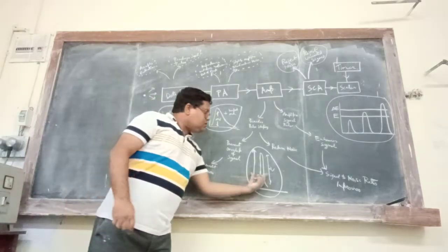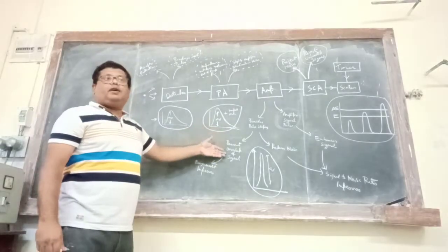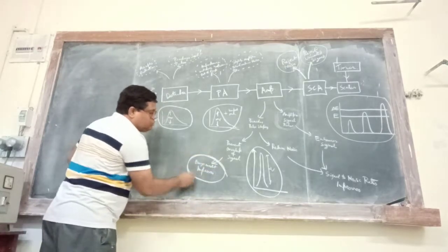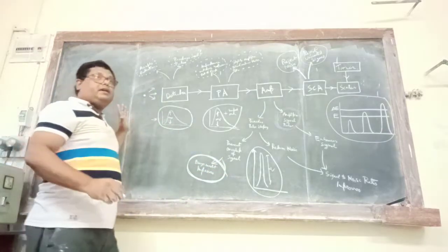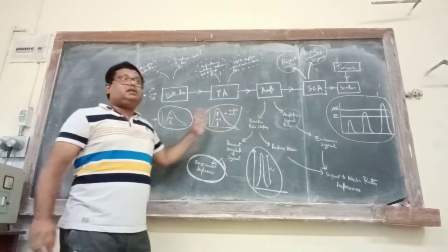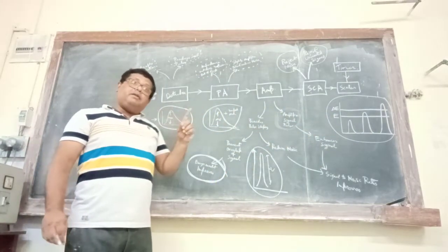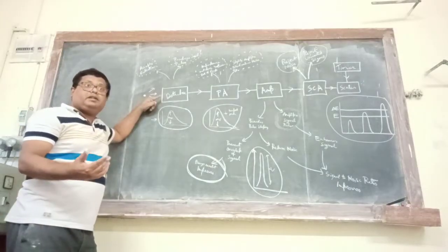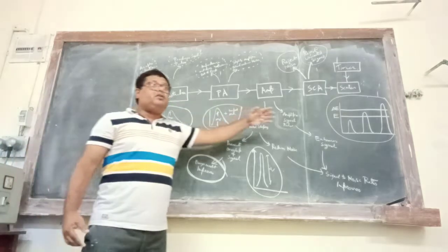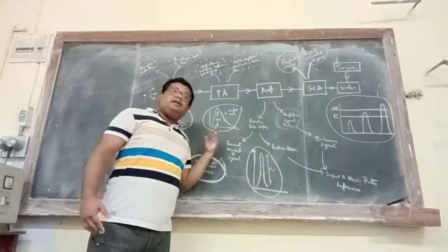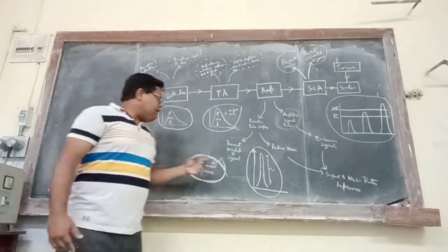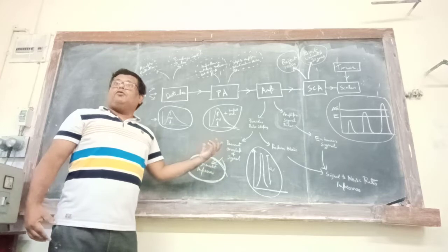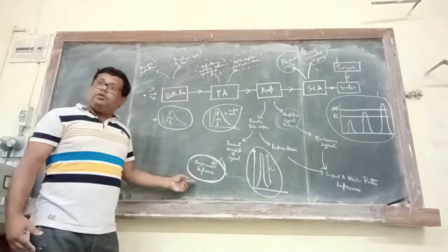And because of this, preventing overlapping of pulses, the energy resolution will improve. Overall energy resolution due to the counting system. Remember what I am saying. Previously I was talking about energy resolution as a property of the detector, but all these components have noise in themselves, right? They can affect the signal width as well, and because of this, preventing overlap of pulses, energy resolution will be improving.